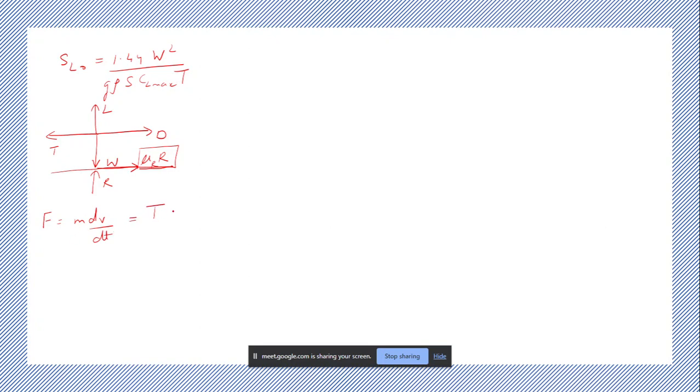That is thrust minus drag minus this frictional force, which is mu R into R. Now if you write the summation of the forces, the equilibrium for force in the vertical direction, you have R plus L equal to W. So R is nothing but W minus L. Now we'll just substitute this quantity here. So what do we get? We get thrust minus drag.